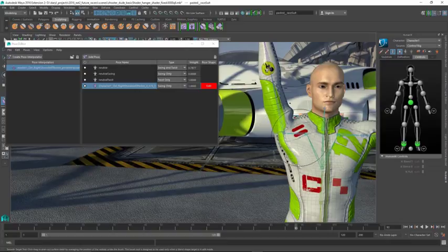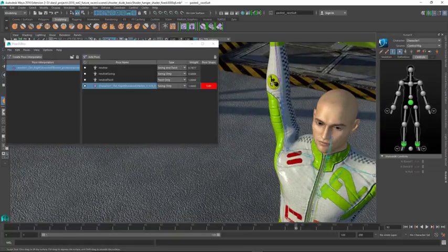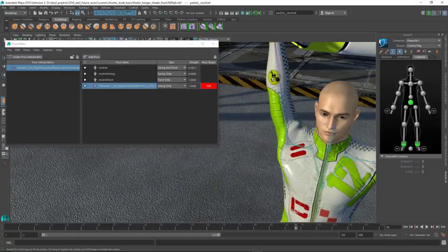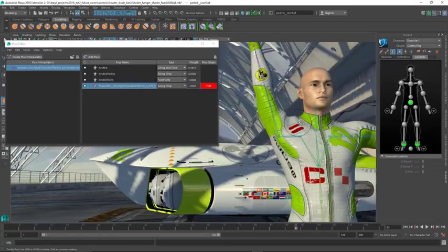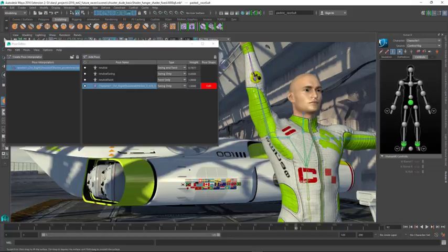At any given time, instead of just a grab brush, I could go in here and use just a simple sculpting brush. If I wanted to really drive that area up a little higher right there and really lift that shoulder, I could do something like that, and then go back in here and smooth that out a little bit. So just by using a combination of painting and smoothing, you can really start to get to an effect that looks a lot better than it did before. I might even want to smooth this region right across there a little bit more.